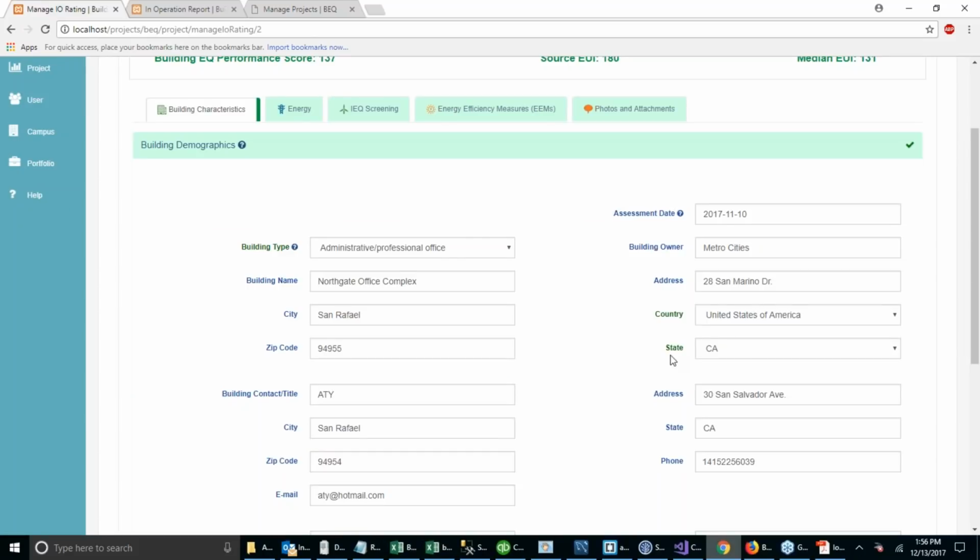It doesn't matter what building type it is. You need to put in heating degree days, the cooling degree days, the climate zone. All the fields that are in green as opposed to in blue will allow you to get a score up top, even if you don't want to do the level 1 energy audit and submit for a rating. All the level 1 energy information is required to submit for a rating, but you can get a score without doing all that.